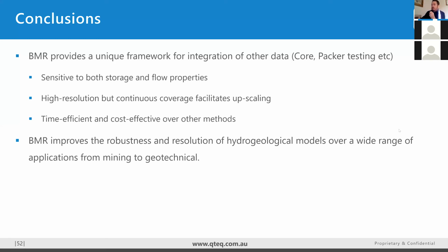And then from that drop in head and the time, they can back calculate a hydraulic conductivity. So from an operational point of view, this often has to be done on a rig. So rig time is expensive, and packer tests can typically take from a few hours to days. And you also have to do something with that water.